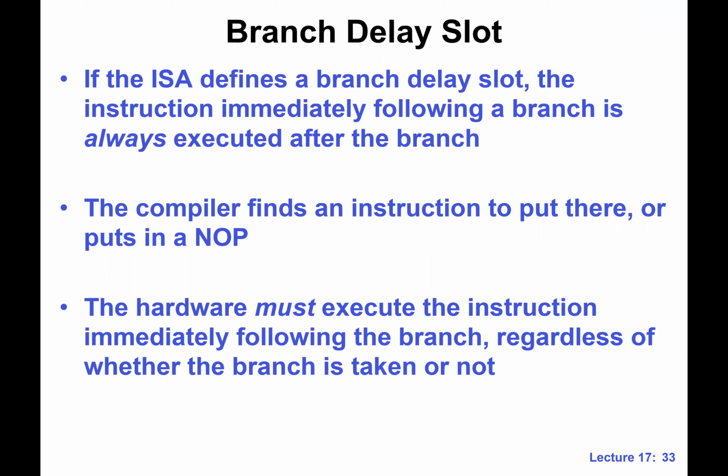So really, we want to make a contract, right? We want to add additional specification in the ISA so that the hardware knows that when we are running a branch instruction, the one that immediately follows the branch is going to be harmless. That one's harmless. It's always going to be executed unconditionally. This is where we introduce the notion of branch delay slot. In this delay slot, it can be a useful instruction or a no-op if you cannot find one. So that's basically the same idea behind the load delay slot.